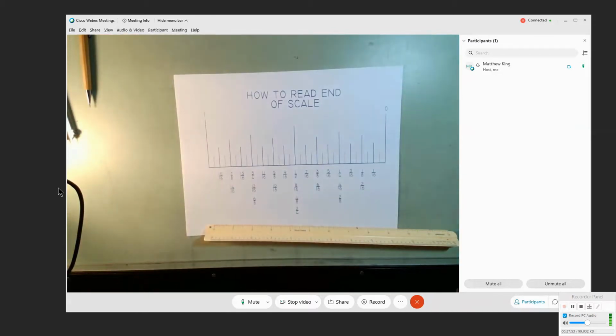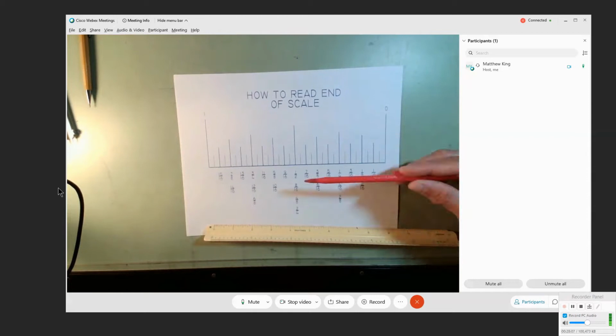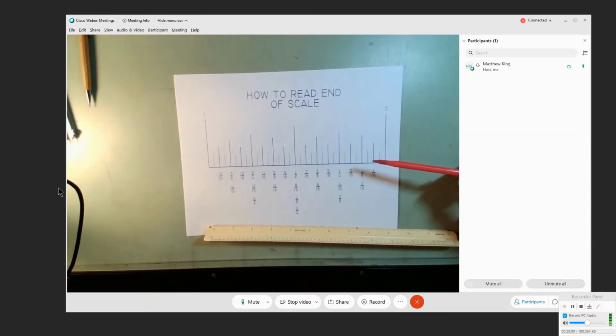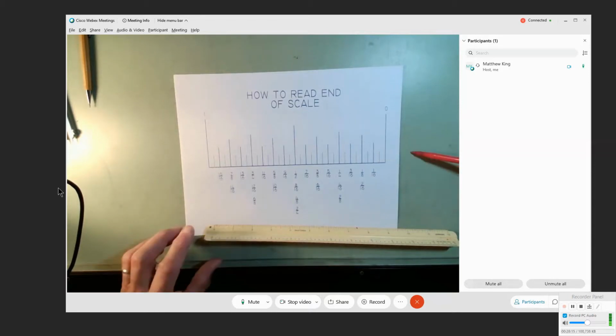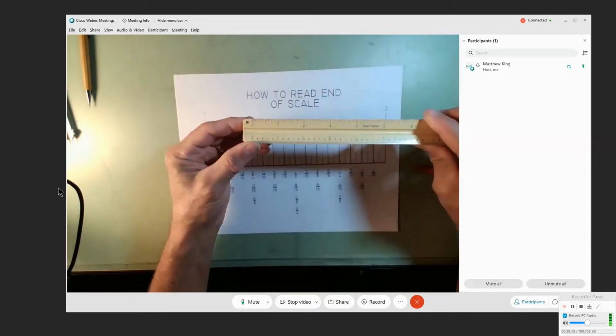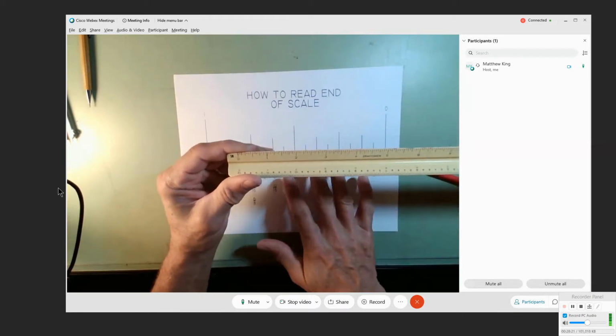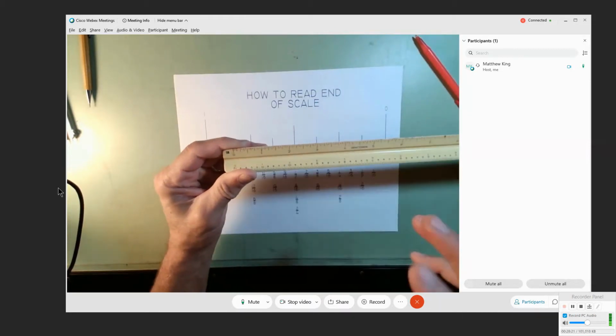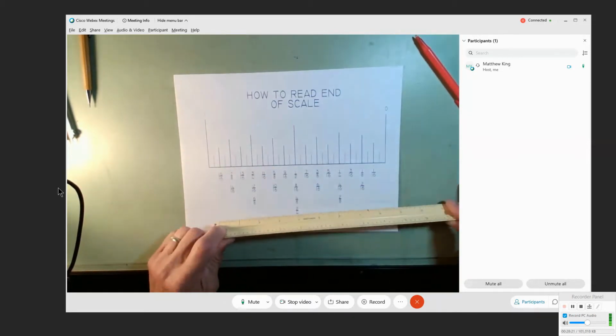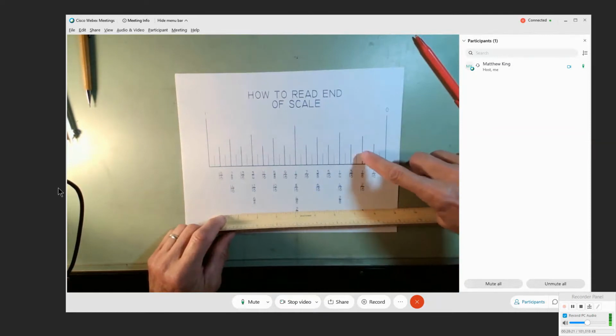And what I'm specifically referring to is the way these little graduations, these lines, these increments are laid out on here. There's more than there needs to be. And these really thin, short ones really don't need to be there for now. All right? They are not on this scale. And that can potentially cause you a problem until you realize that. So you really need to ignore these tiny ones.